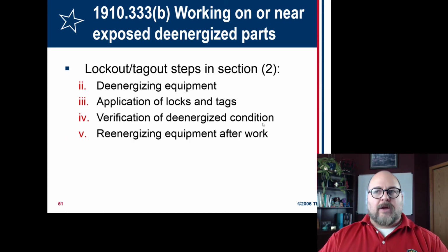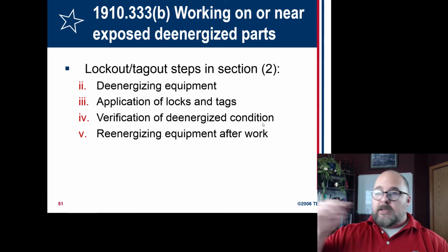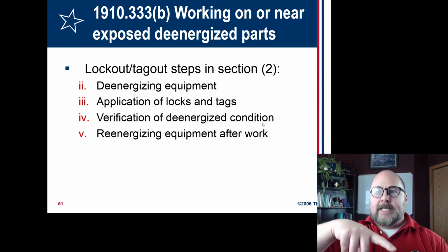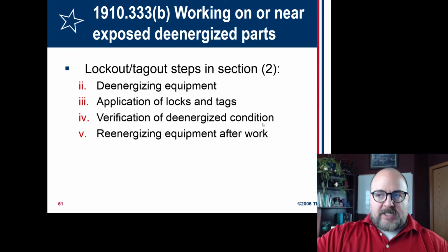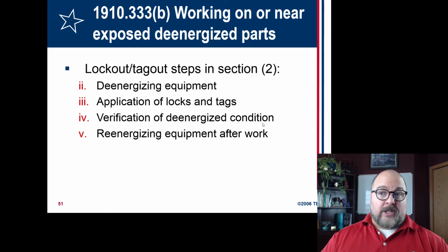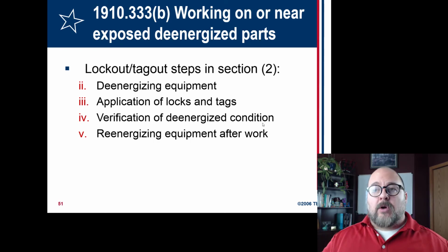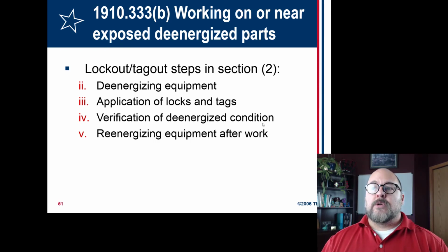Lockout tagout basically, and this is just for electrical, and there are other forms of energy that need to be isolated or de-energized and controlled, is that if somebody's going to work on a piece of equipment, you want to make sure that piece of equipment isn't running. Not only do you not want them exposed to electrical hazards, but you don't want the machine to start up, because that can cause problems too.